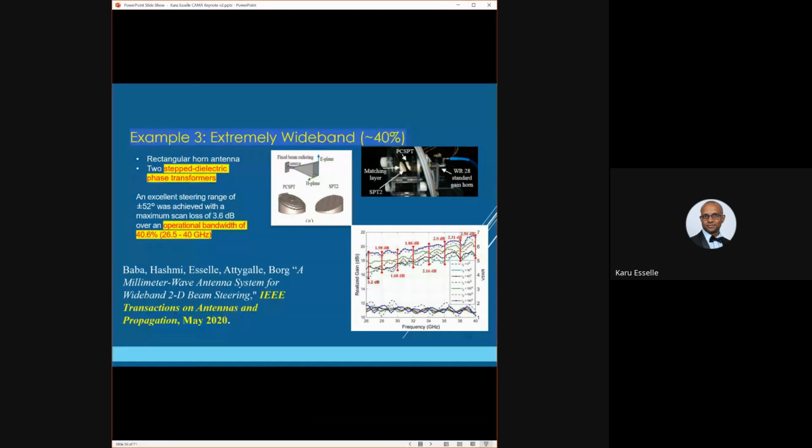So all these cells in the metasurface are supposed to be totally transmitting, or at least close to ideal transmitting elements, not reflecting. So the transmission coefficient of the cells normally we want them to be greater than minus 1 dB. Some of the worst ones could be minus 2 dB, and we try to avoid cells that are reflecting. That is very important when we design the cells, phase transformation cells. They should be transparent, not reflecting.